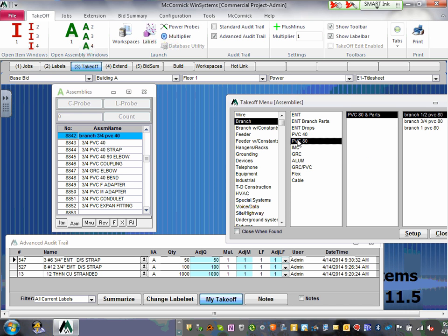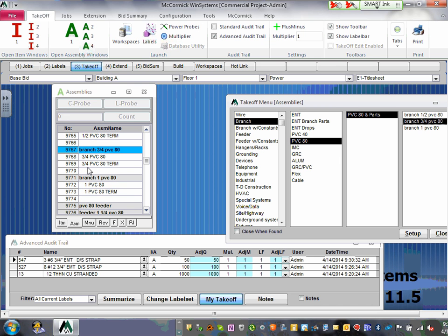Schedule, yeah, 40 or 80. Here's 80. Parts, half an inch, 3/4 of an inch. Here's the 3/4 of an inch PVC. Doesn't have conductors. It's just conduit. The 2 ones they're going to be using as EMT, 3/4 of an inch, number 8. Okay. The next thing I would like you guys to go to is MC cable.